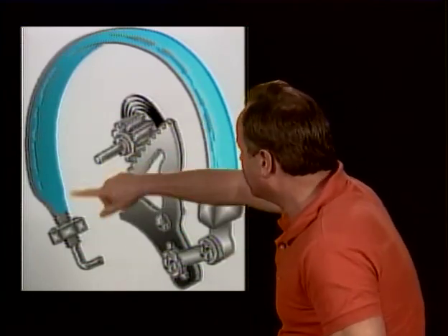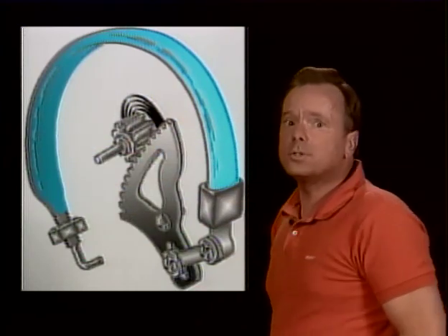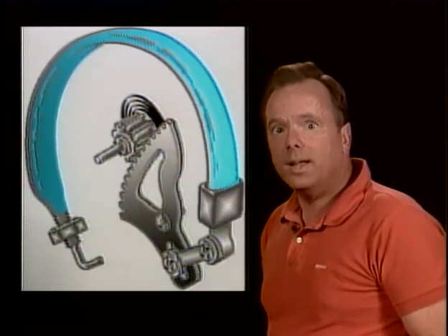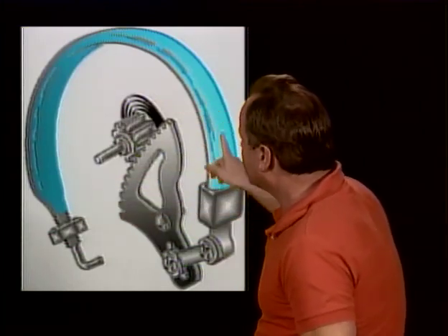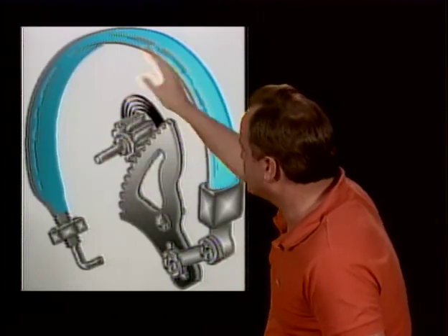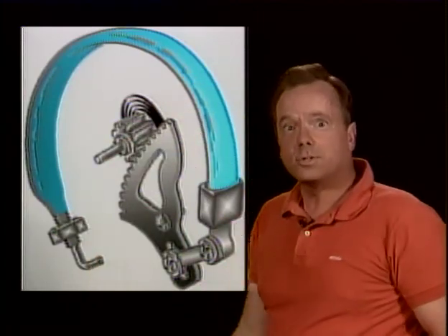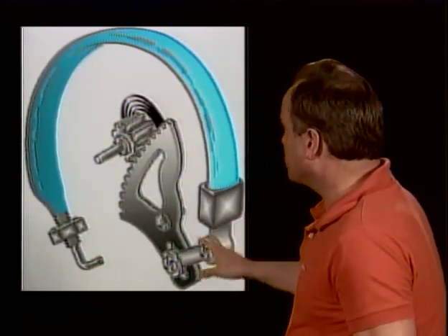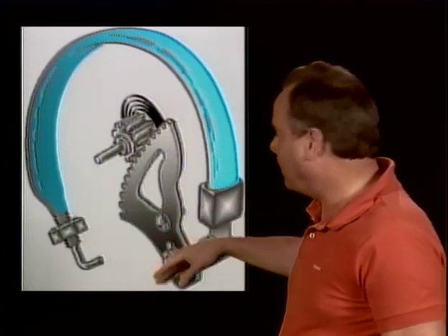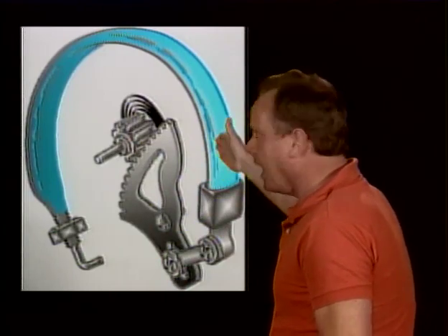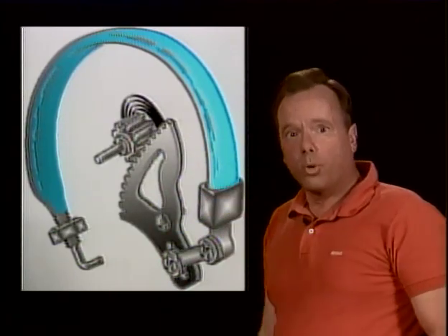And that's called a Bourdon tube, and it indicates pressure. You can also use this to indicate temperature, by the way. The way you do that is you put a very volatile fluid in here, and when the temperature increases, the pressure increases, and once again, it tends to straighten out this tube. So you can indicate pressure or temperature, but oil pressure gauges tend to be the Bourdon type, and if you have more than 10 psi, the FAA wants you to know you'd probably use a Bourdon type gauge.